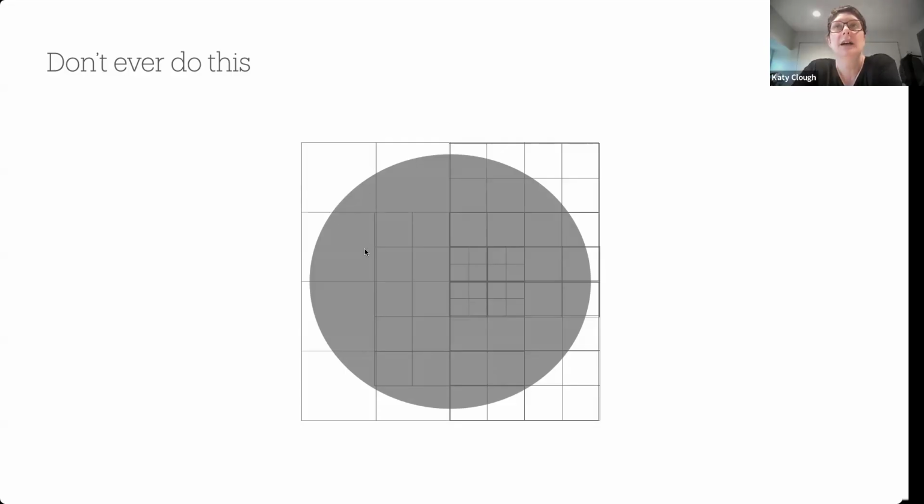If you tick in boxes, you have to make sure your boxes are multiples of the regridding box size you use in the adaptive mesh, so that you always get whole boxes refined. This is always a bit painful.